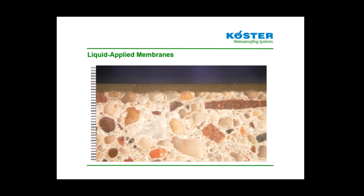This is a cross-section view of a 15 mil 100% solids epoxy coating, very similar to the VAP 2000 moisture mitigation system, which was applied to a shot blasted concrete surface. You can see the roughness of the surface where the aggregates are exposed. That provides that tooth for bonding of the epoxy to the concrete. The continuous film has sufficient mil thickness to serve as a barrier to moisture movement. If installation is done inadequately or improperly, and there are areas of the film that are too thin or discontinuous, it may allow moisture to transmit into the adhesive in flooring, leading to failure.